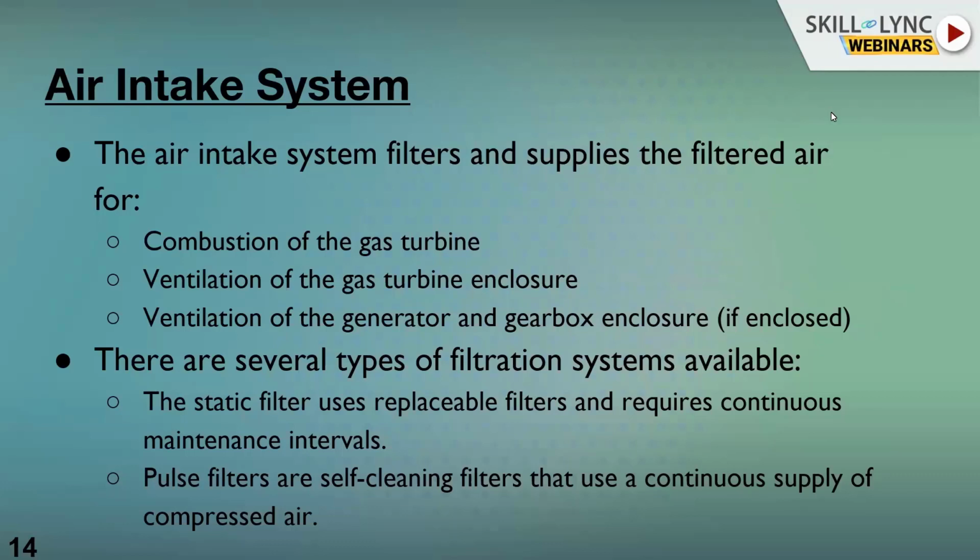And if there is a generator and a gearbox connected, we have options to ventilate that area as well if it is enclosed. In case the generator and gearbox are left out in the open, then we don't need ventilation for this system. Okay, and what are the different types of filtration systems available for the gas turbine? We have something called a static filter and a pulse filter.